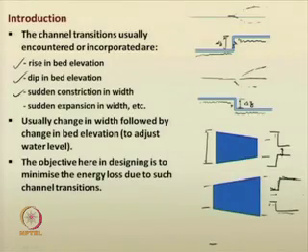So, therefore, to maintain the water level almost in a similar way, if the channel width is increased, then it may be followed by a decrease in the bed elevation, or some sort of change will be there. So, our objective mainly is, while designing, we have to minimize the energy loss during the channel transitions. With that objective, one will be going for designing the channels in flow or flow in the transitional forms of the channels.